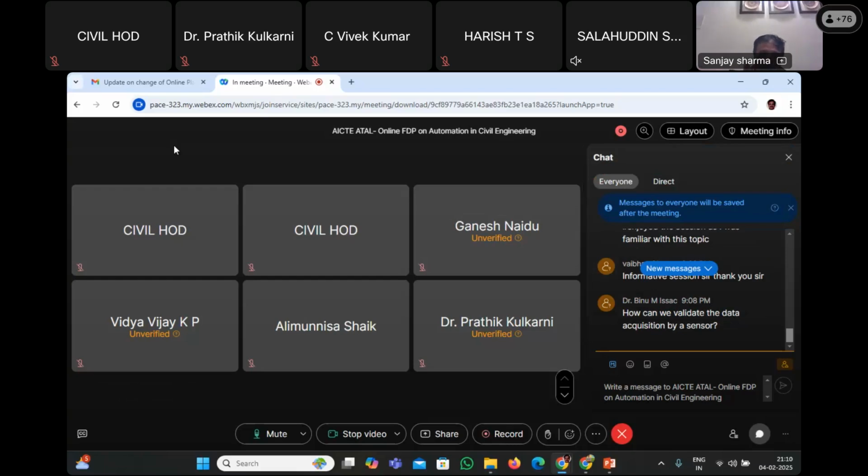and the core we took was 800 mm. So we knew the depth of this raft foundation. Then we carried out all the tests, like the strength test for the column and beams, and found out what the concrete strength is, how many bars there are, the number of bars, the spacing of bars. So we gave every data to the designer, and he designed the things basically.